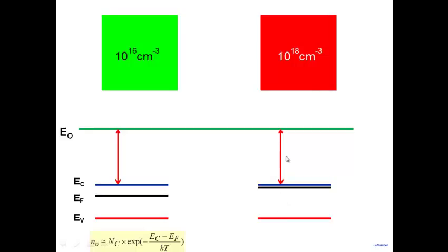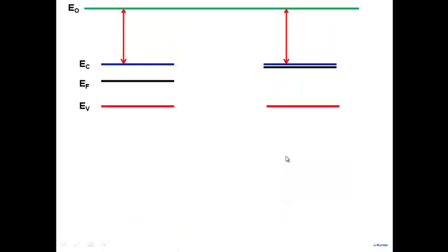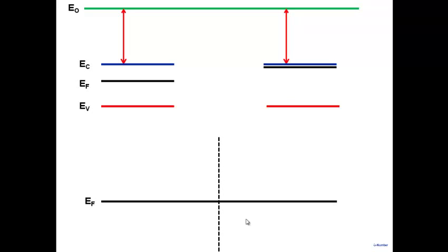Okay, so let's sketch the energy band diagram in equilibrium here. In equilibrium, the starting point is what? Constant EF. No longer constant E0, because note that a field and a voltage is already developed. So E0 is no longer constant anymore. So a constant EF is what you draw. You draw EF throughout the system. The next thing you draw is a line indicating the interface between these two materials here. Okay, draw a line here. The interface between them. This side was, remember, all 10 to the power 17. This side was 10 to the power 18.